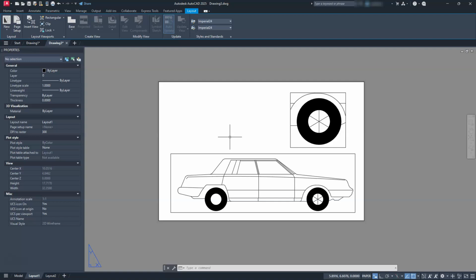Don't put a weird scale on your drawing, right? Don't put something super crazy on your drawing and say, hey, this is a weird scale factor of, like, 5, although you could do this, 5/32 is equal to a foot. It's probably a lot easier to make it not to scale because they don't make an actual scale for that. So that's kind of to sum it up.